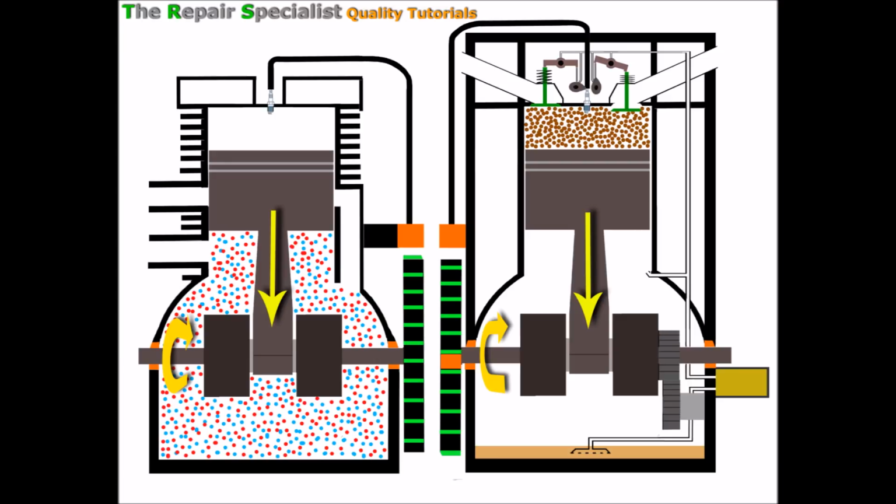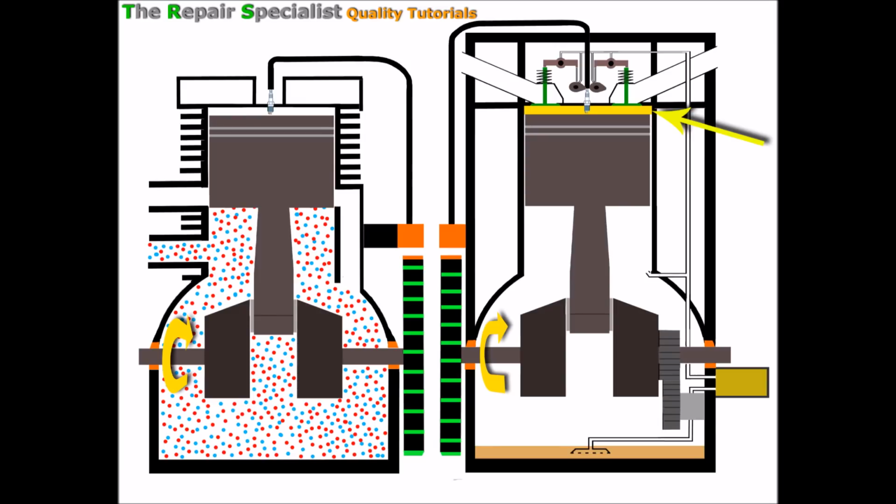So an important thing to mention now is that until this point, where the four-stroke engine is now generating power and forcing the piston down itself and creating its own movement, the movement of both engines was down to the starting process from either the starter motors or the starter pull cords, etc. And of course, because the two-stroke hasn't yet created any combustion for its own movement, it's still moving from the operator's starting process. But for simplicity, let's still imagine that they're moving at the same speed, but they most probably wouldn't be in reality.